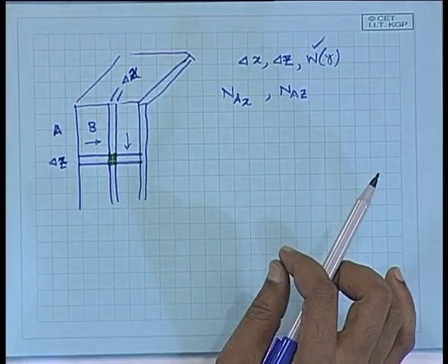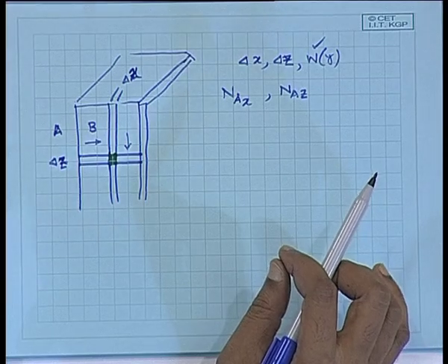So, if it is a non-reacting system, mass in minus mass out, considering all the two directions, there is no reaction, it is a steady state. So, the sum of that would be equal to 0. All right. So, no reaction term and it's steady state. So, no change in concentration of A at a fixed location with time. So, the accumulation part, the right hand side of that equation, is also 0.